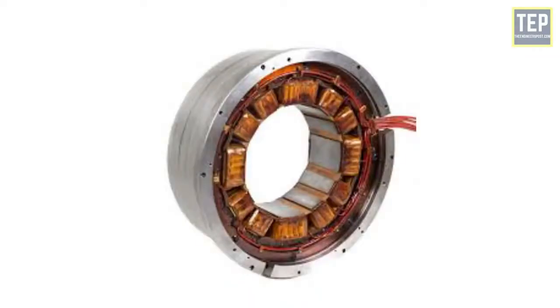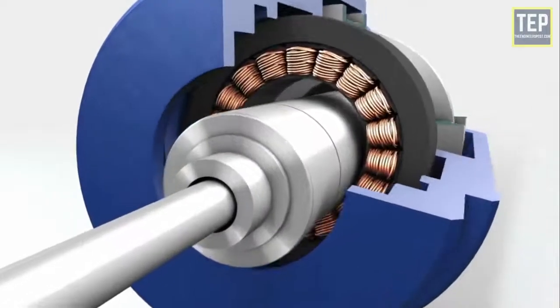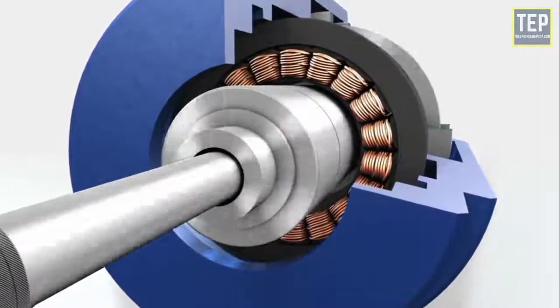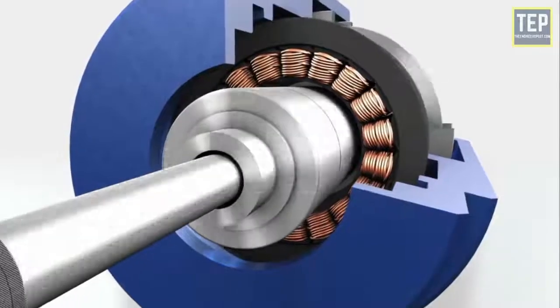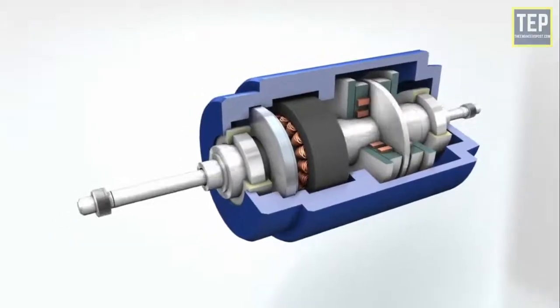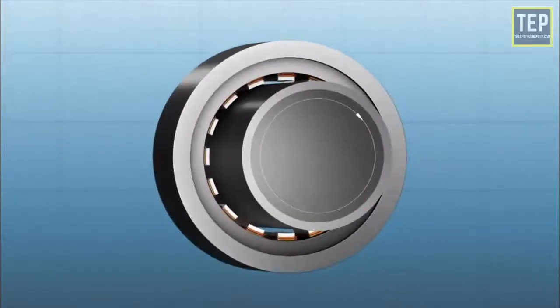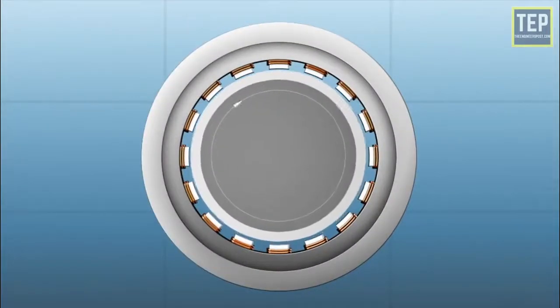Magnetic bearings use the concept of magnetic levitation to hold the shaft mid-air. As there is no physical contact, magnetic bearings are zero-wear bearings. There is also no limitation on the maximum amount of relative speed which it can handle. Magnetic bearings can also accommodate some irregularities in shaft design, as the shaft's position is automatically adjusted based on its center of mass.